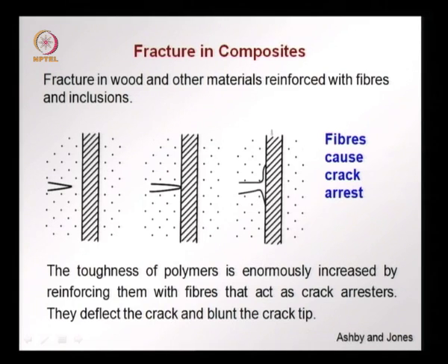Secondly, some of the stress now is transferred by the fiber. So there is less of a driving force for continuing the crack, because some part of the stress now is transferred from one side of the material to the other by the fiber itself. So the toughness of the polymer is increased significantly when fibers reinforce polymers, they act as crack arresters, they deflect the crack and they blunt the crack tip.